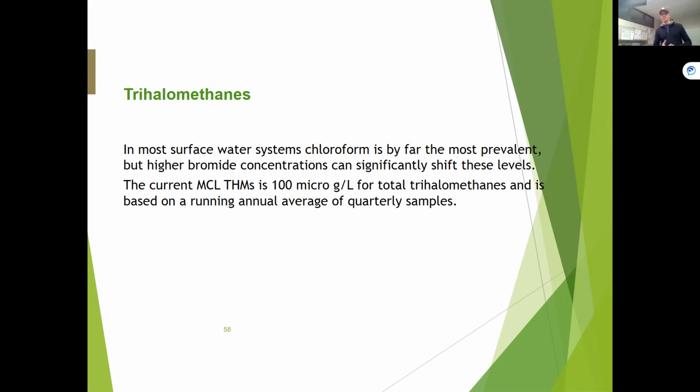And these are not easily removed in a wastewater treatment process. So now these are starting to come into our treatment plants. Because they're dissolved and not easily removed, there's no mechanism. And also, think about it: we add chlorine to these things. So we chlorinate different things. What are we creating in compounds? As we're moving forward as water treatment professionals, always keep in mind that there are always going to be things coming up. I think the next big one of concern that we all need to be aware of is these pharmaceuticals that aren't removed in the wastewater process and get back into the system. And now potentially when we add chlorine to them, it could cause us some issues.